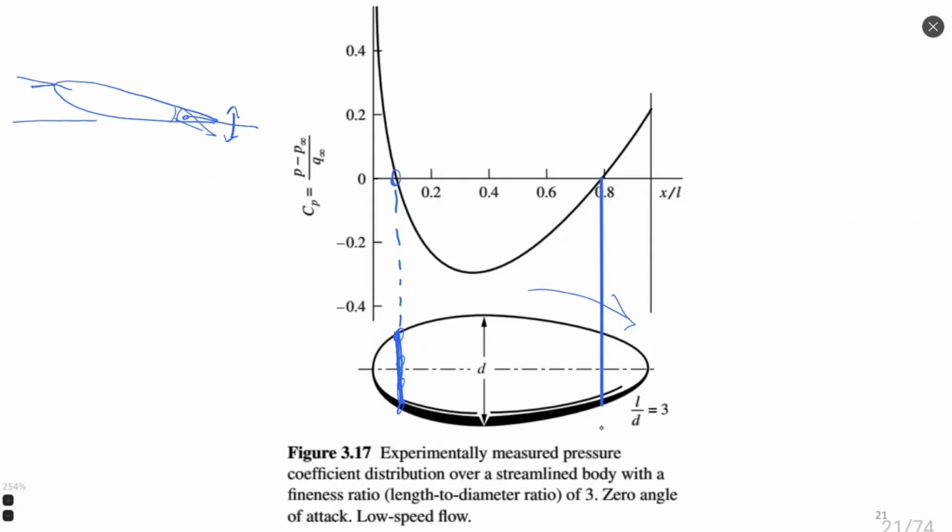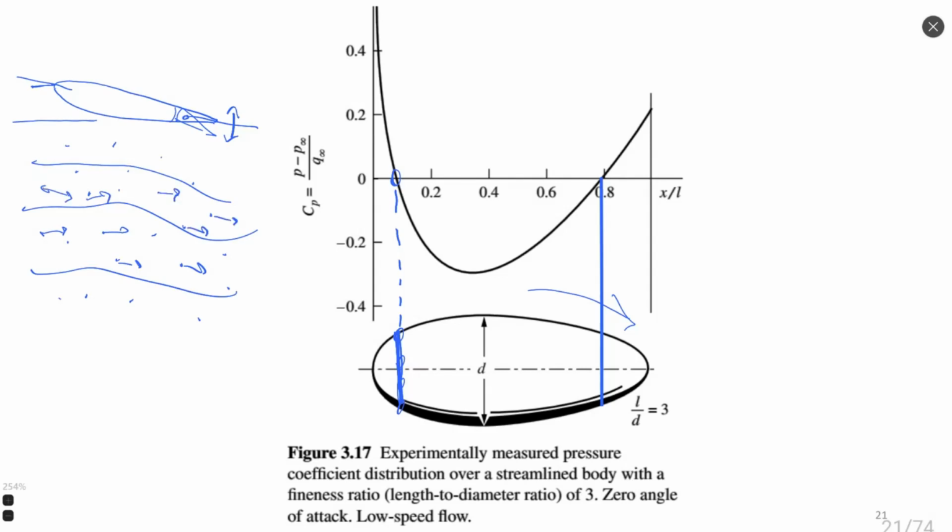I think one of the most advanced methods is when we have a flow, or arbitrary flow, and we put small dots inside, very light particles, small particles, inside our flow, and we track these particles with some hardware system, and by this tracking we can understand direction of flow and flow velocity. This can be done by modern methods.